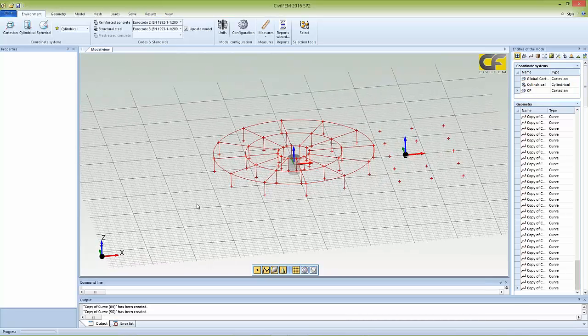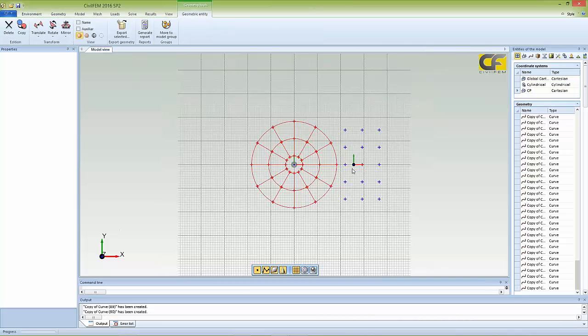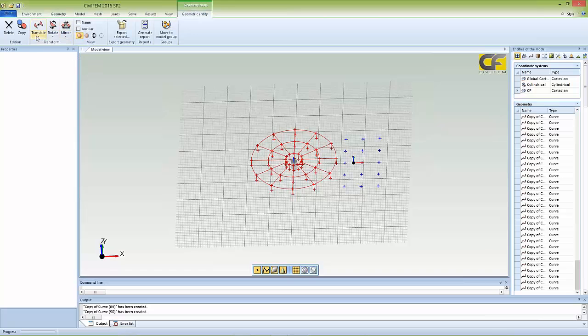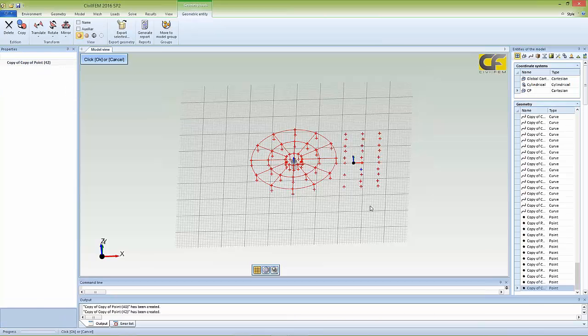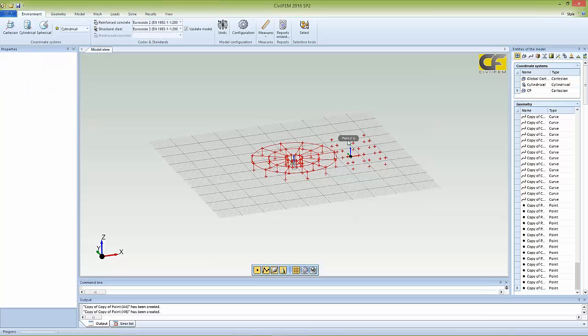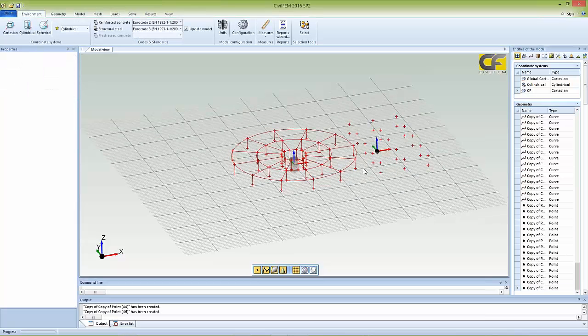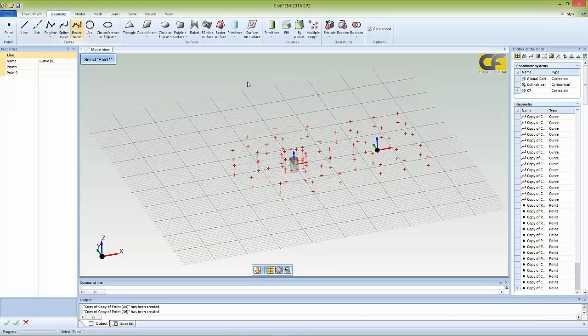And we will apply the same process to the rectangular building, and we could just observe the steps we're doing. First step will be to project copy in the vertical direction the full height of the rectangular building for 1 story. Now we're going to create portals in the X direction and the Y direction for subsequent copy.